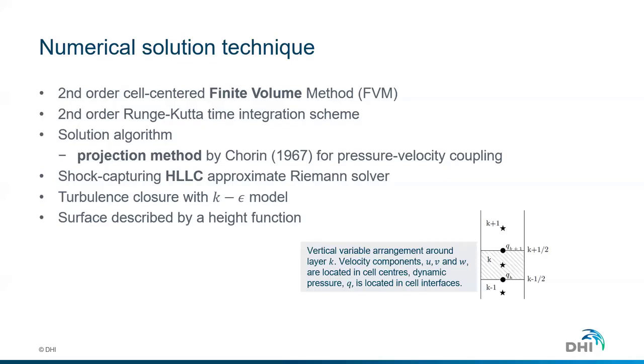Then we have implemented the software with a shock-capturing HLLC Riemann solver, allowing us to reconstruct the intercell fluxes in areas with discontinuities in the surface elevation. A case where this will happen is when we see waves shoaling up and breaking. In those areas, we will introduce discontinuities in the surface elevation, which is handled by this HLLC Riemann solver.